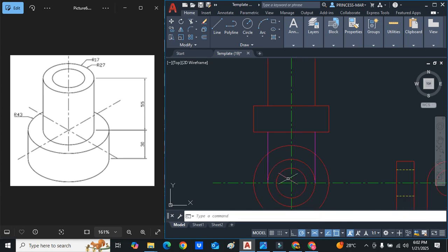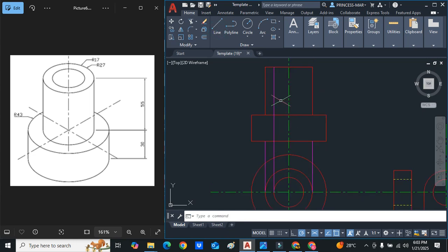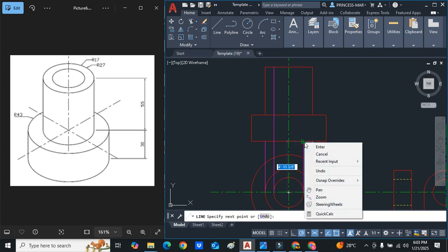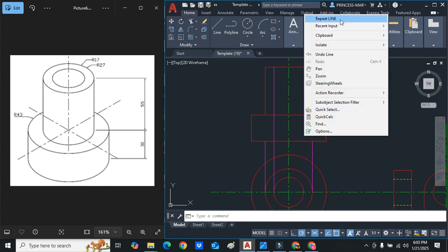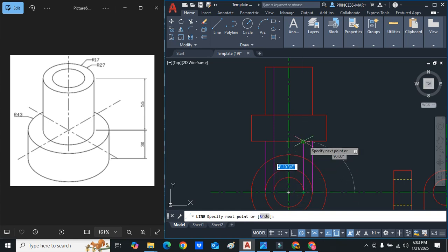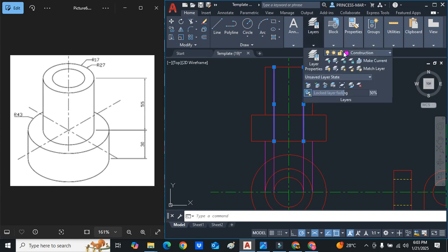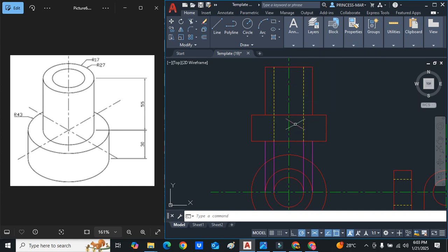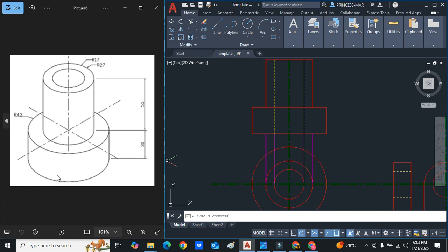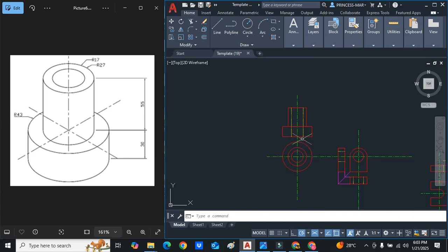Now you realize that the smaller circle is missing. That smaller circle is going to be in hidden detail, and it's going to go through the entire figure. So right to hit the bottom, then it comes up. So that is our hidden detail line. So this is our front view. So we can see the thick rectangle at the bottom, the smaller one to the top, and we can see the hidden detail for the holes going through. I'm just going to delete these constructions.